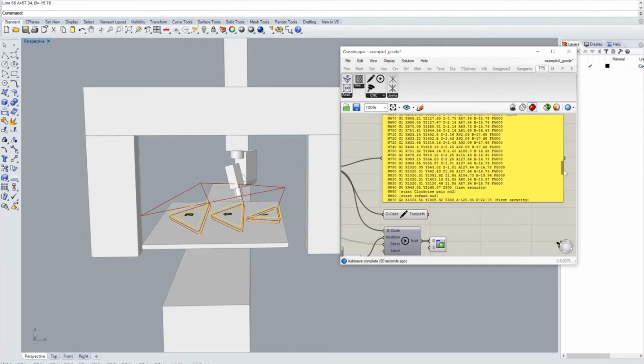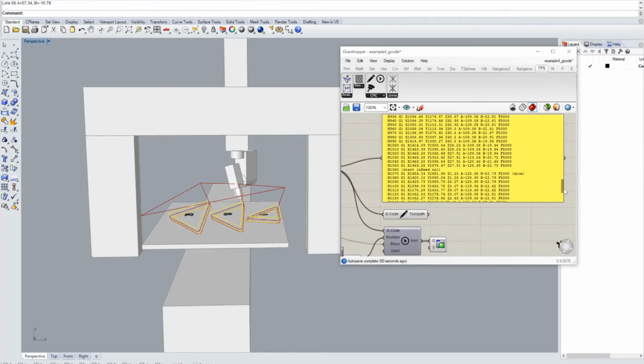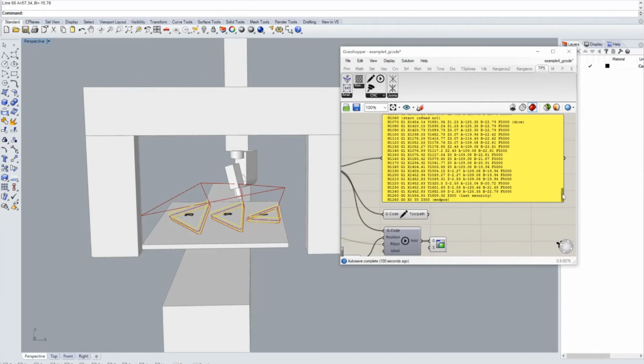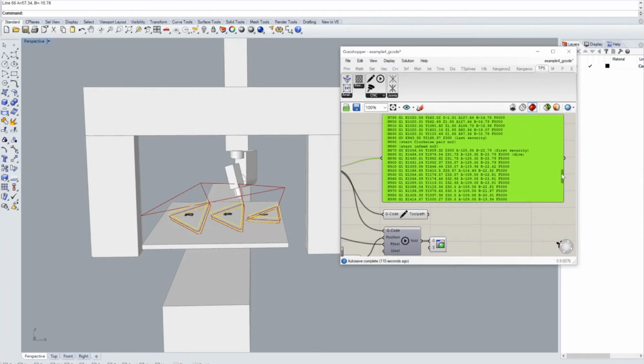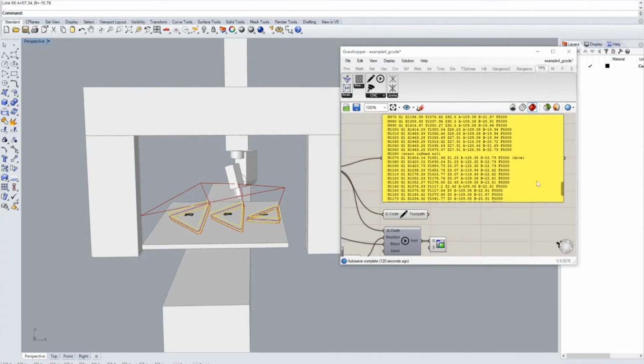It is also going to tell you when it goes into second pass. So here you see start in feed number 1, that's the first pass, and for this part there's going to be no second pass. Oh yes, because it's counting down. So it starts with the clockwise pair number 2, and then it starts with the in feed number 2, and then it counts down to the last in feed, so number 1 is the last one. So that's how that works.